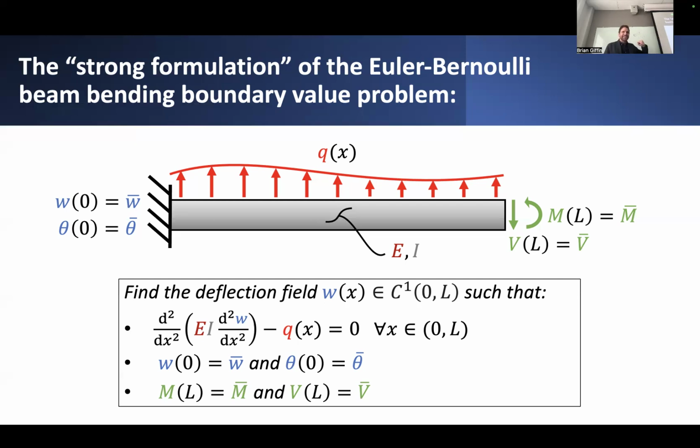Now, in the case of solving these more simplified beam bending problems, the notion of boundary really has a different interpretation. Technically speaking, the whole boundary does include these lateral surfaces, including the surface on which we're applying this transverse load Q. But now, boundary is probably more well-defined as really just the ends of this beam.